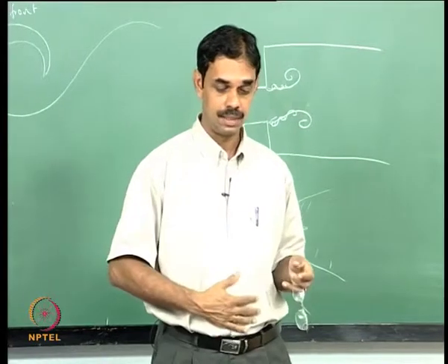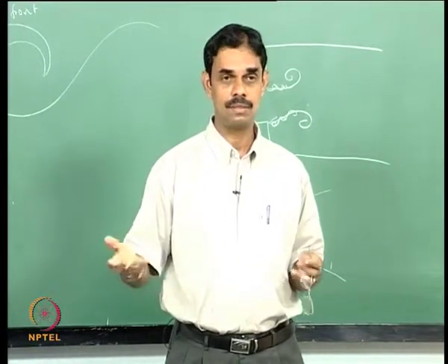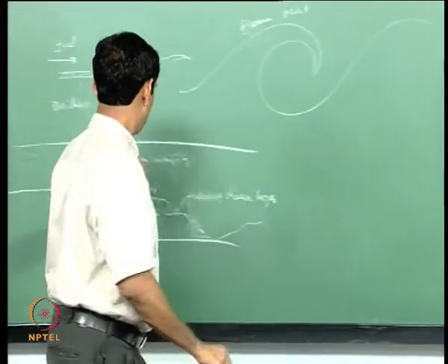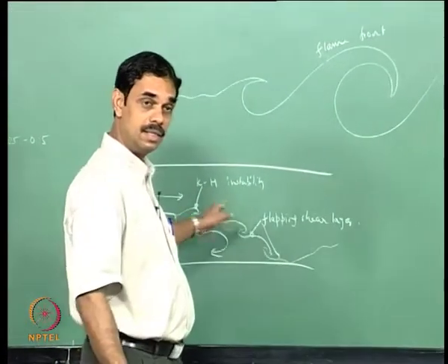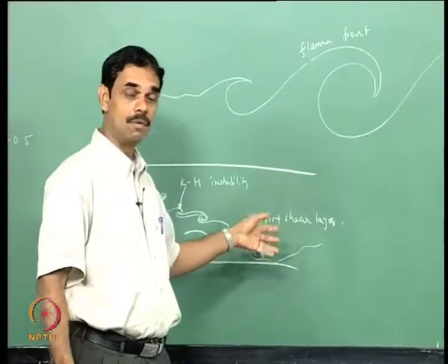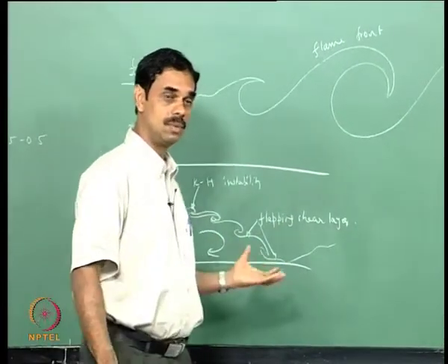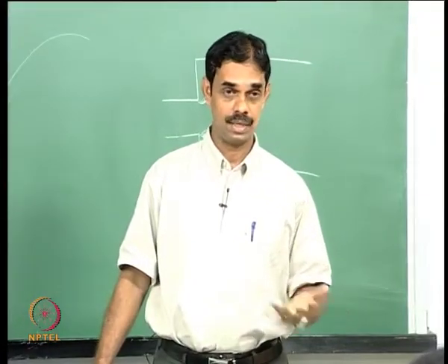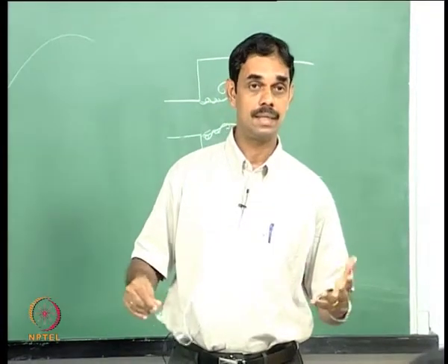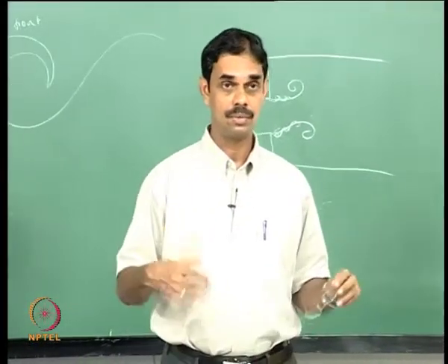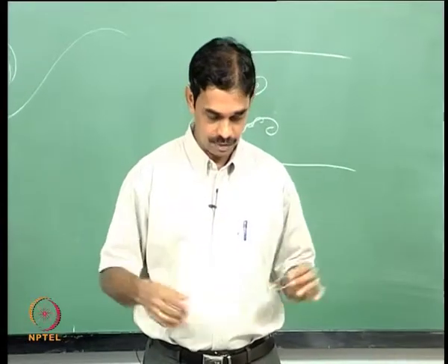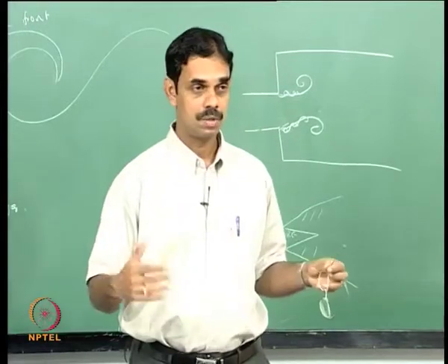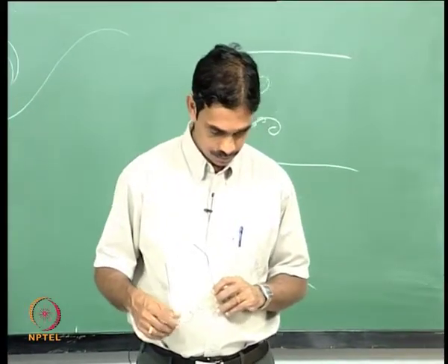If it is out of phase it will not be adding energy, and sometimes some part of the flame may be adding heat in phase, some other part may be adding heat out of phase. But what matters is the net energy addition to the acoustic field. Some part may add, some part may take out, so the net energy addition is what decides whether you are going to have acoustic driving and instability or not, and whether the net driving is actually more than the losses or less than the losses.